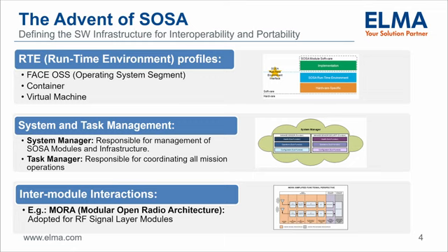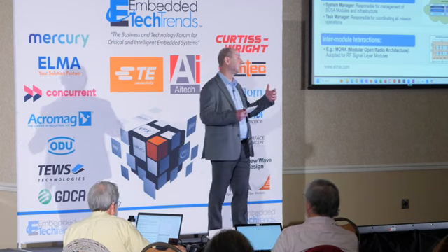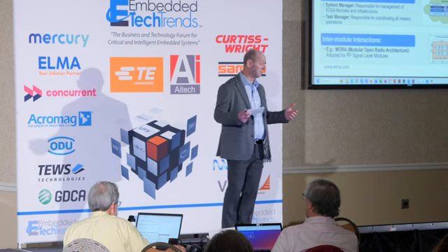As well as hardware though, it really goes into a lot of depth defining software. One of the keys here is defining the platform on which all the SOSA sensor applications must run, and that is the runtime environment profile. It defines 3 runtime environment profiles, which I'll talk about in a minute. It also defines the infrastructure for management of the hardware and the modules via the system manager part of the specification, and also the management and coordination of the mission operations via the task manager.